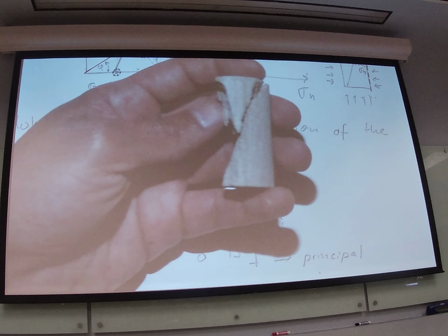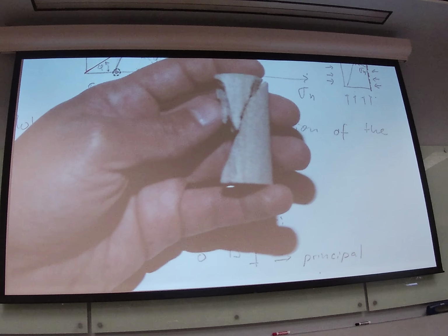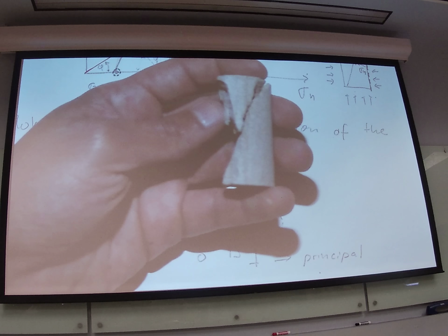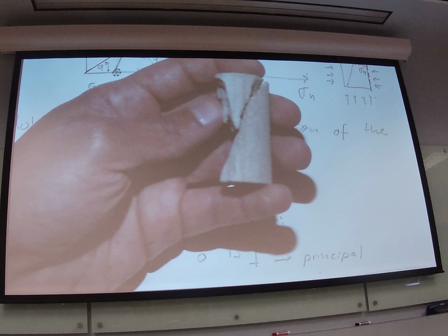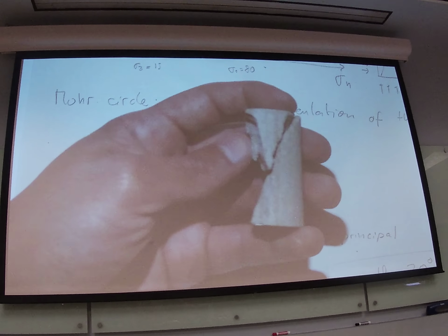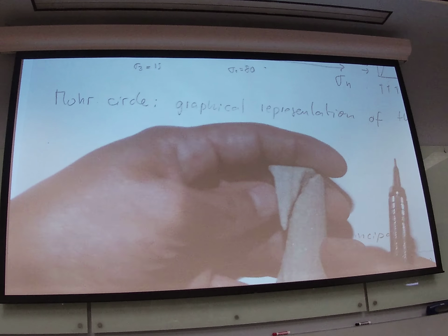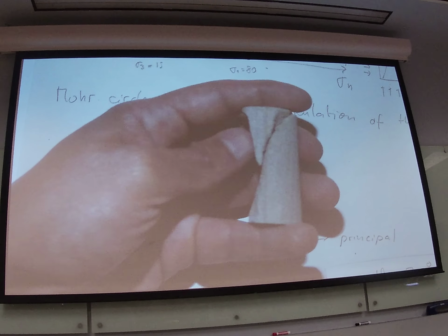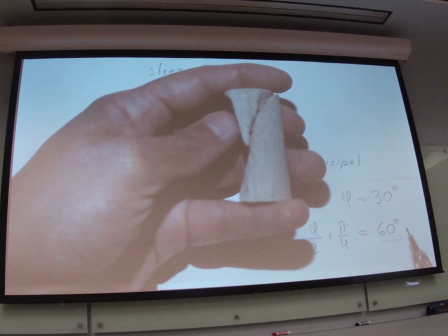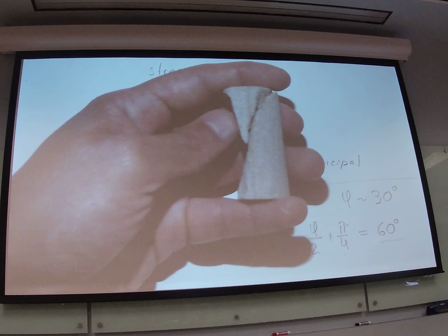How much is going to be phi divided by 2 plus 45 degrees? It's going to be 60 degrees, right? But let's just keep it just this 45, this 15, this is going to be 60. And that's an angle higher than 45, and it's always around this value. So it is in a steep angle.